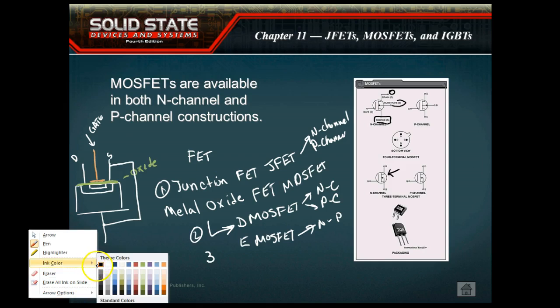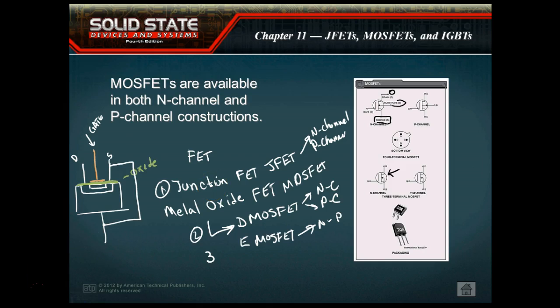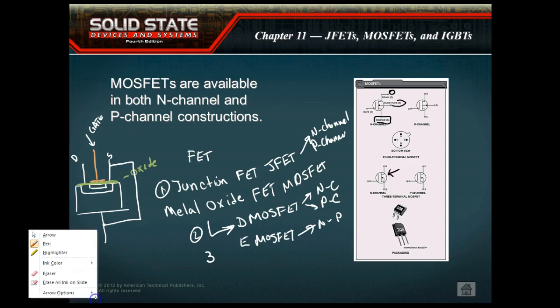So you need to keep these guys in static foam. A lot of times when you buy an FET, it'll have a little wire spring wrapped around the leads to keep the leads from ever getting at a difference in potential. And this causes a problem because sometimes people forget to take that spring off. What you're supposed to do is solder them into your circuit card so you can handle them. And then the last thing you're supposed to do is grab this little ring and pull off that little spring clip. It's got a little ring that sticks out from it.